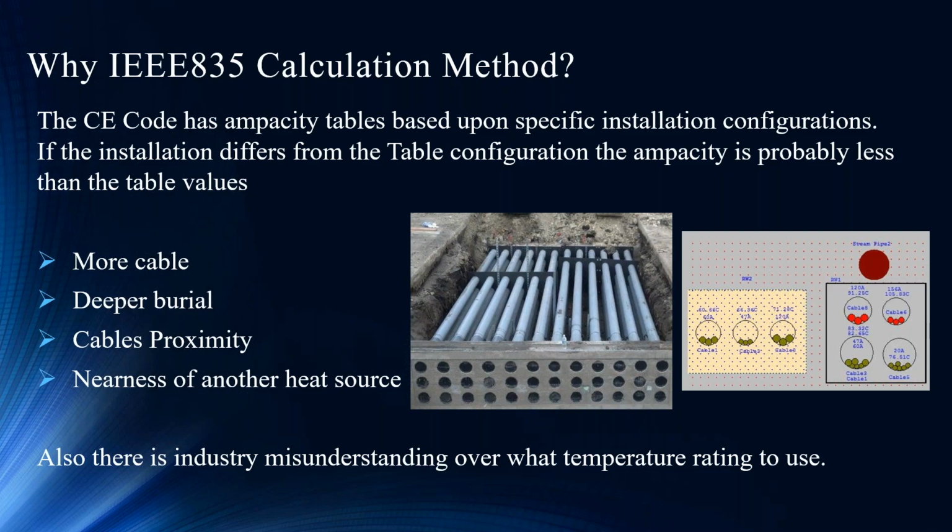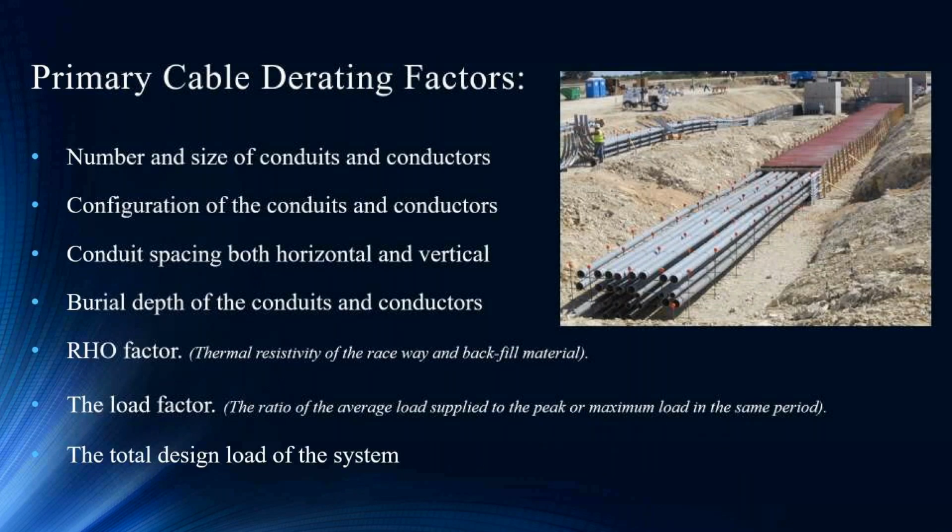I know that in industry there is a kind of misunderstanding that the deeper we bury the cable, the better it is. I think they think it's going to be mechanically protected, but it's otherwise. Basically, the deeper you go, the less heat transfer you have, and it's going to overheat the cable. Each of these variables can affect the temperature rating and ampacity of the cable and requires further investigation. In the next slide, we're going to look at just one example.